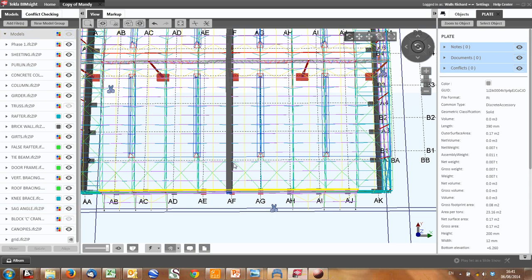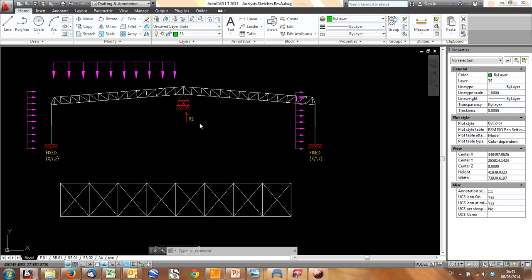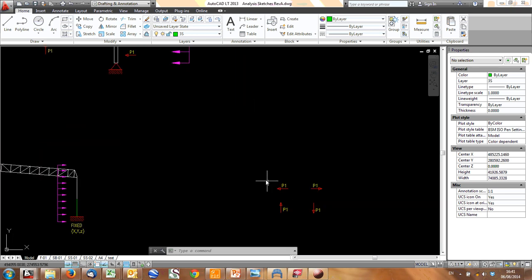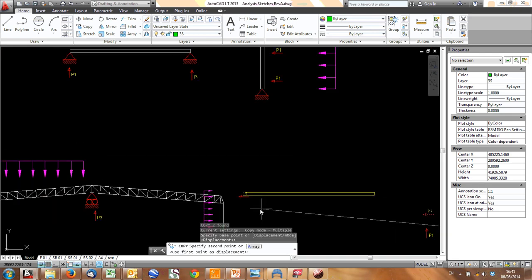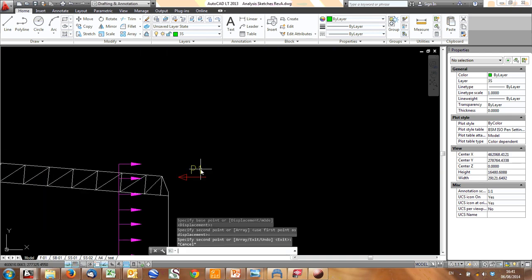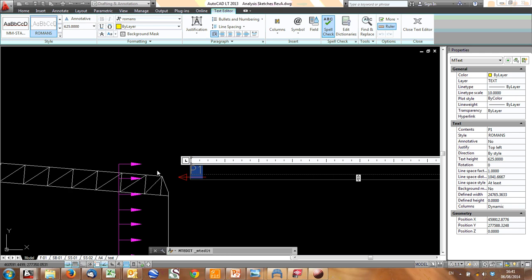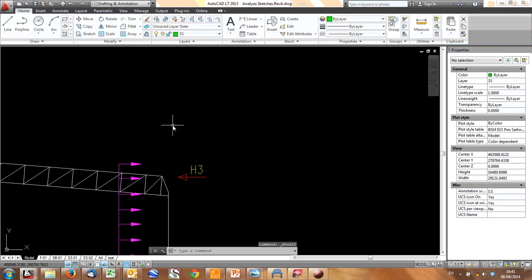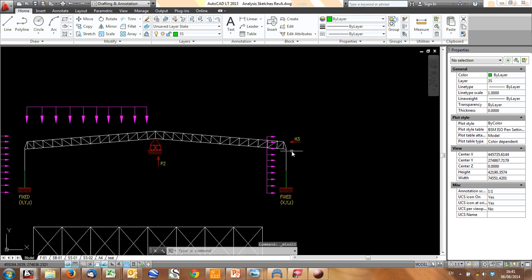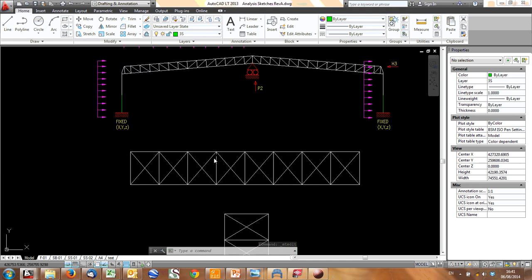And once again, where do these loads go? So now I can analyze my truss. I get a reaction. Let's call that P3 now. Maybe we'll call it horizontal load, just so you don't get confused. There we go. Horizontal 3. There's a horizontal prop. It is carried by this. This now is carried by this truss.